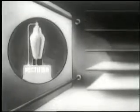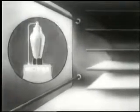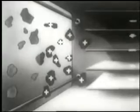This diagram explains how the precipitron works. The rectifying ability of electronic tubes is used to apply a potential of 13,000 volts DC to tungsten wires and 6,500 volts DC to collector plates. As incoming air passes through the field of these wires, each particle of dirt receives a positive electrostatic charge. When the positively charged particle reaches the collector chamber, it's attracted to and deposited on negative plates.